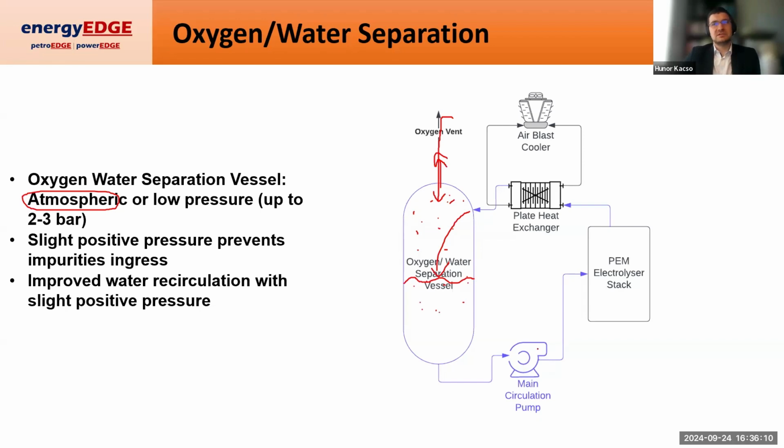That is for a few reasons. By the way, one of the reasons is that on the surface of the membrane, the bubbles will be smaller because you have that ever so slight increase in pressure. Therefore, you're covering a larger area of the membrane surface.